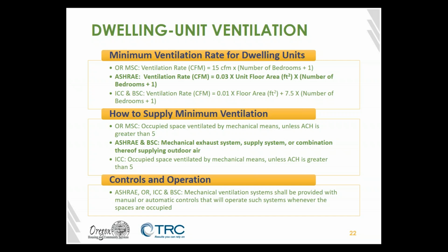Some of these guides do allow for intermittent, right? Ones that turn on for 4 hours or 2 hours and turn off at other times and take an average over the day. Those are probably on their way out over time, right? It's a much better strategy for indoor air quality and health to just continuously operate fans. And fan energy has gone down and down and down. That's just the direction that the world is going.